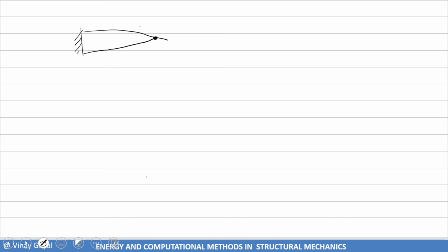And the curve here is given by x to the 2/3, times a constant, of course. So the cross-sectional area there is going to become that. To me, that's an exciting problem because it shows the use of optimization, calculus of variations, to show that if I apply load P, I can minimize the deflection, keeping the volume constant, and to make that happen, the area has to be distributed in that manner.